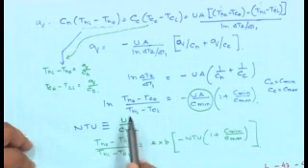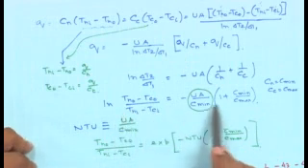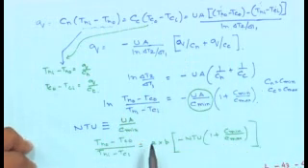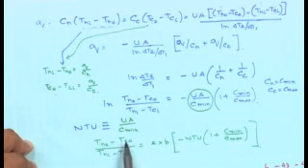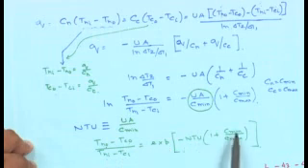And therefore, upon simplification, what you get is simply this factor, and therefore the temperature change at the hot inlet temperature, hot outlet temperature and cold outlet temperature divided by the maximum temperature drop that can take place is going to be exponential minus NTU 1 plus C min by C max.